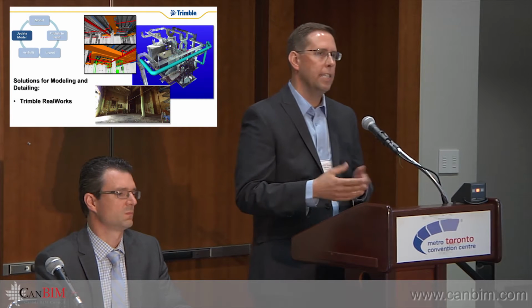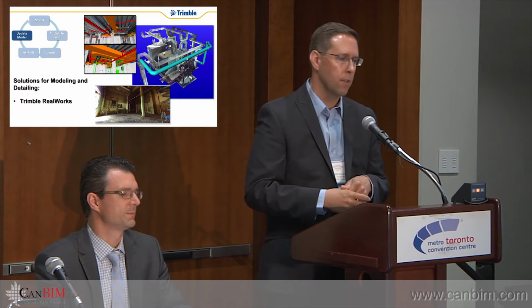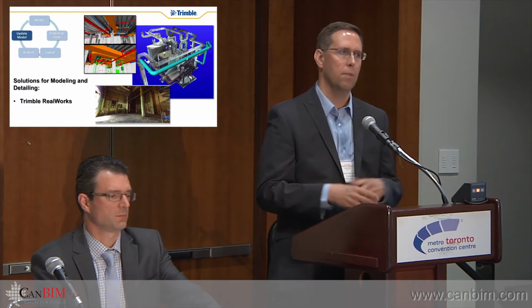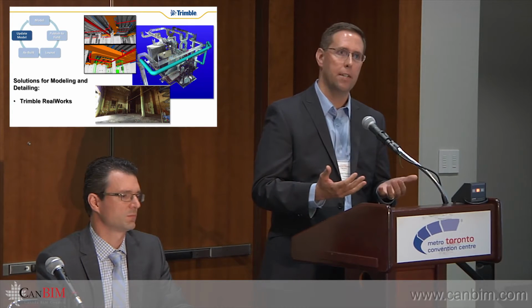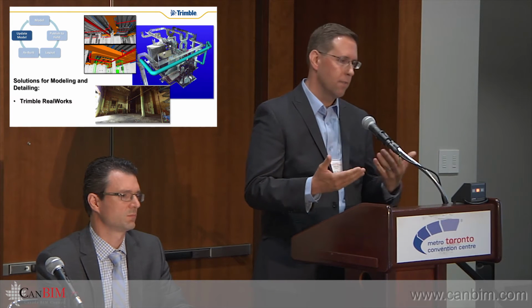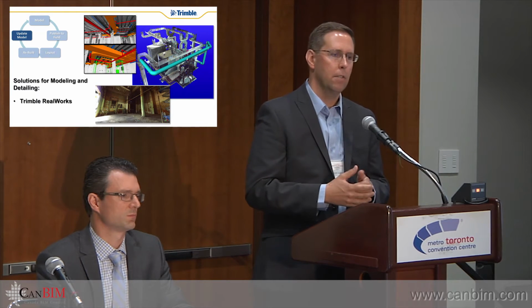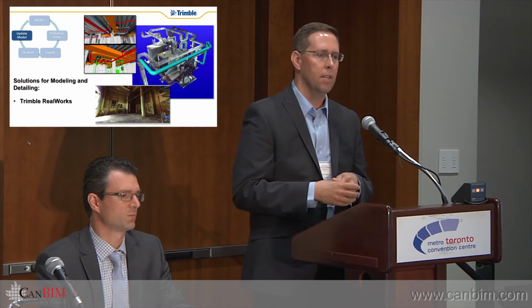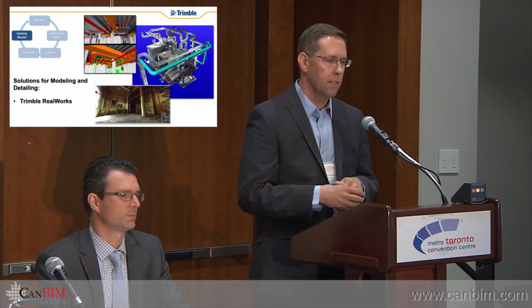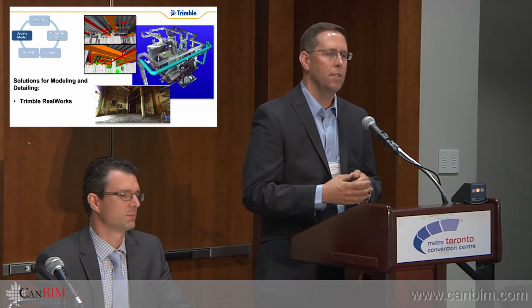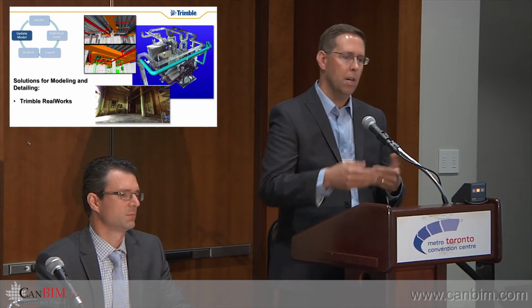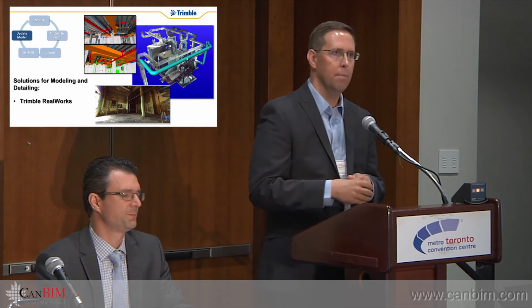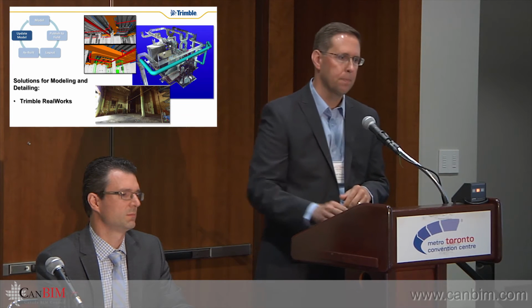And then other ways that you're seeing updates being made to the model, you're also starting to now see 3D laser scanning come into play with the MEP workflow. And the solution that Trimble provides is our scanning software called Trimble RealWorks. And what this does is it allows you to take a 3D laser scanner, go out into the field, document what I like to refer to as the as-is condition, and then create a composite 3D point cloud model that then represents the actual conditions that you're dealing with. And then from that point cloud information, you can start to do detailing and modeling of that point cloud, and then push both the point cloud data and the model data into your other CAD and BIM applications.